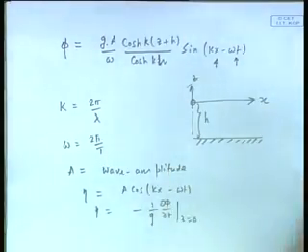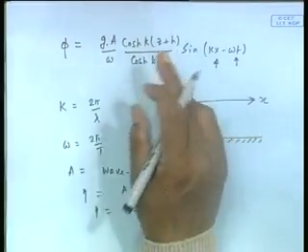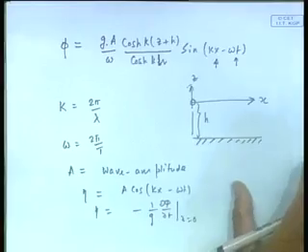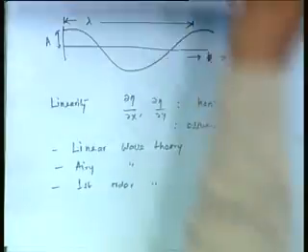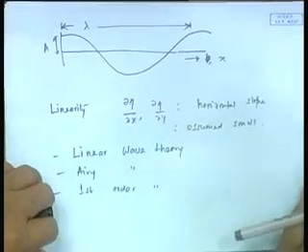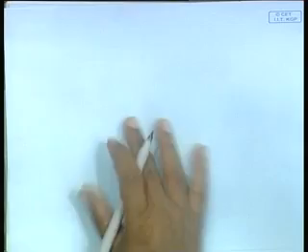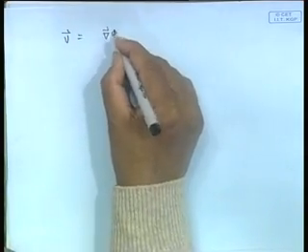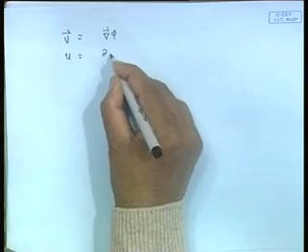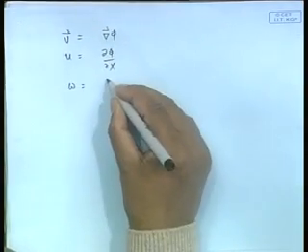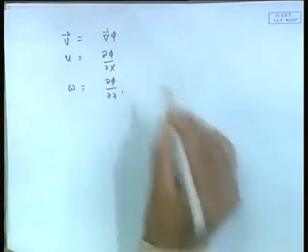So, therefore, if I were to take a gradient of phi with respect to either time or with space, it would also be sinusoidal, and it turns out all quantities of physical interest are actually gradient of phi. For example, if I want to find out velocity, say v of the particle, it is given by grad phi, that means u is given by d phi by dx, w vertical velocity is given by d phi by dz.